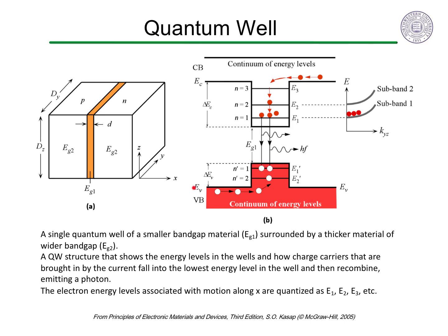Likewise, the valence band maximum acts like a potential well for holes. The smaller band gap in the active layer leads to a band offset and the potential well for both electrons and holes. Instead of free electron-like band states, the states in the well region are quantized to particular energies because the well is so narrow. The quantized states are called subbands here as they still have free electron-like dispersion in the other two directions. They are only quantized in the thin direction.